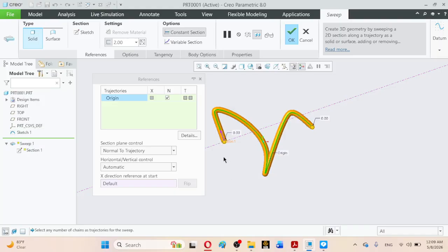So actually only this important point was to be explained, but here I have now observed, because I have taught many earlier versions of this software, that it actually created issues and problems. So that is why I have tried to demonstrate it. If you have an earlier version, or you might suffer some problem, and you have a trajectory with sharp bends and narrower turns, always use the sweep section having smaller sizes as much as possible, then this command will be successfully executed.